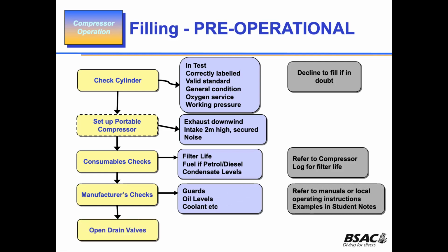Open all drain valves, right? That's pre-operational. Never start a compressor under load. You won't be able to start a little 5.5 Honda compressor if you haven't drained all the air out of the system, because it won't let you go. You will never get it actually running round. The compressor will stop it from getting enough motion to kick off. So that's just a thing.